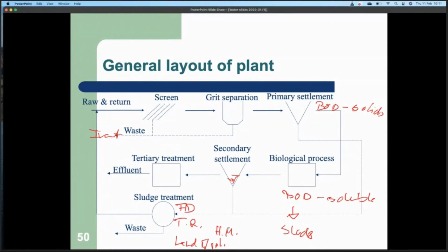And the heavy metals come quite naturally in sewage treatment because the sludge, if you think of it, is nothing else but the biomass that's being generated in the biological process. And biomass, the same as you and I, at the bottom of protein in particular, you tend to have a metal ion, which gives the 3D structure to the protein. So if you're digesting the organic parts of a protein, what you're left with is a metal ion. So that's exactly what happens here.